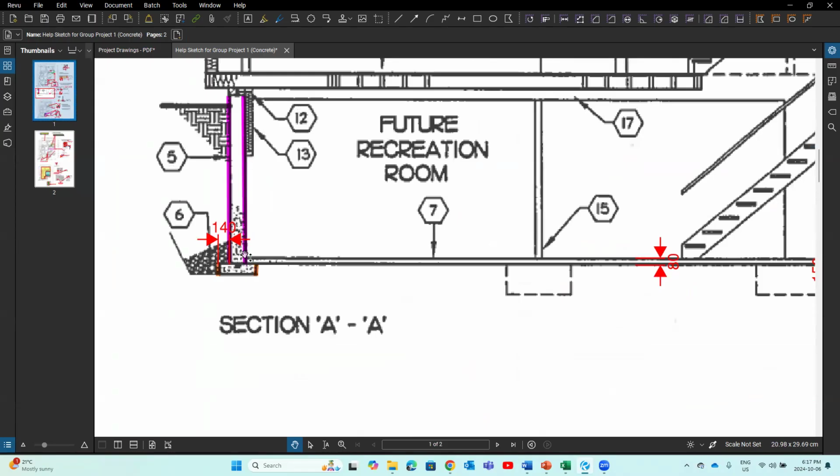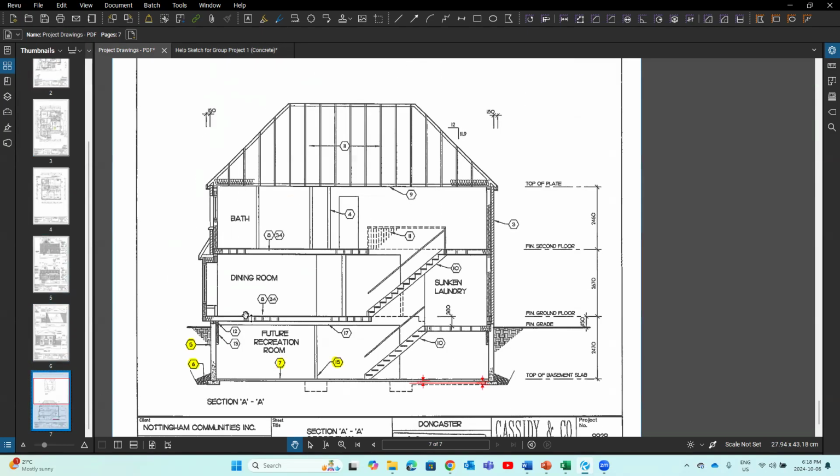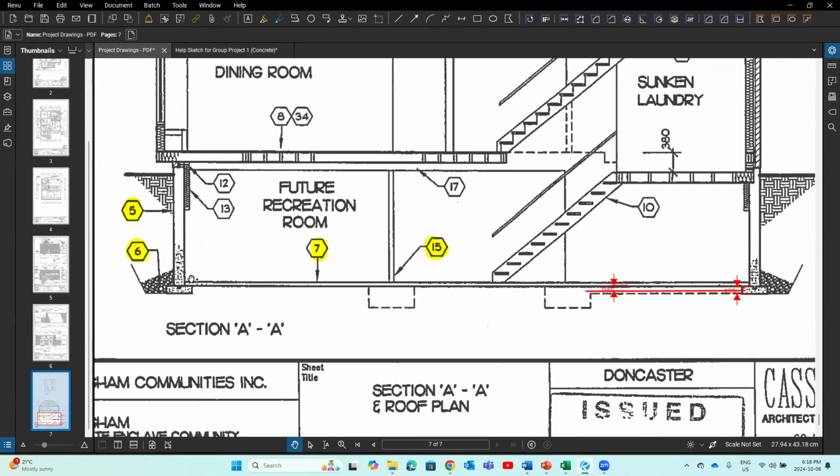You see, normally between the foundation wall and concrete slab, we have control joints. Sometimes we also call that expansion joints, to allow the foundation footing and the slab to have different settlement because of the load, right? The foundation wall and foundation footing have a greater load compared with the load on the slab. If you think about the way you push the soil, right? The harder you push it, the more the soil will settle.